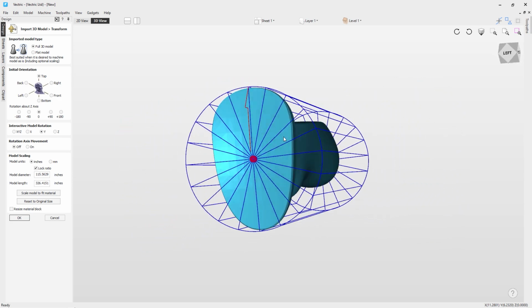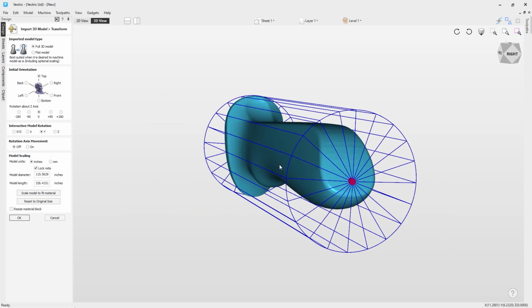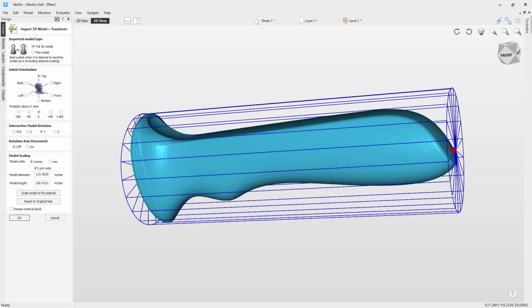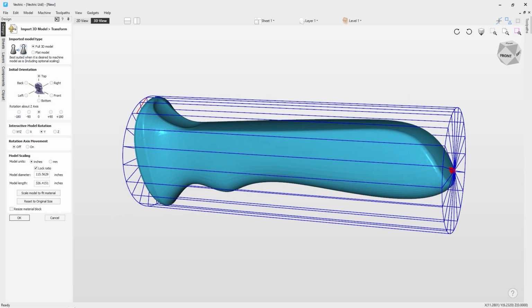And you can see in the front view here, it's pretty central for our axis, but on the back here, it's not quite central. Now that can actually cause a little bit of a problem, and sometimes it's just the best that we can do, and sometimes you may have some undercuts that you're going to have to work with, because when the actual software unwraps this, it will try to fill the space between the material and the axis here, and so the fewer the undercuts we have, the better. So for example, if this happened to be a model of a figurine or something like that, you may not be able to position it in a way that there are no undercuts at all, and you may need to work out how to position that to make the best of that particular model.